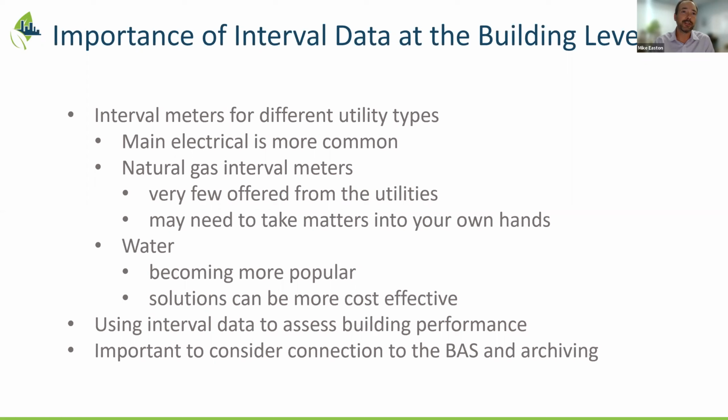One caution we have on this, though, is there are a few different meter manufacturers providing building level water metering across the country. Some of those manufacturers' pulse outputs are very difficult to integrate, even though it says pulse output. In some cases, you're getting really high readings, up to 1,000 pulses a second. That might not be possible for an energy management system or a data logger to collect accurately, so you need to verify that before the installation is done.